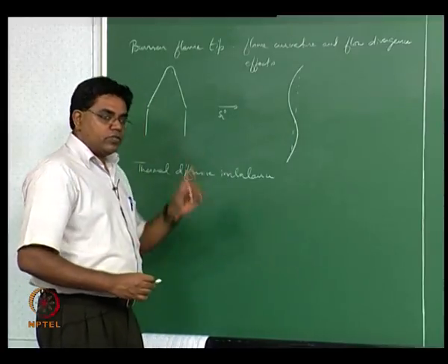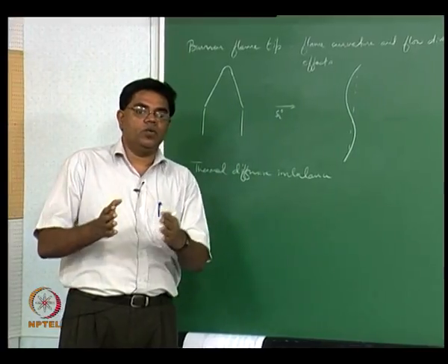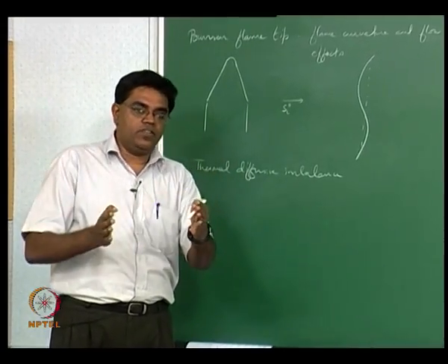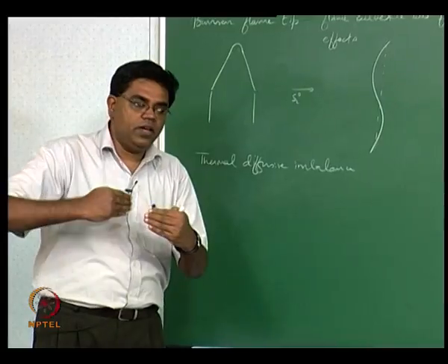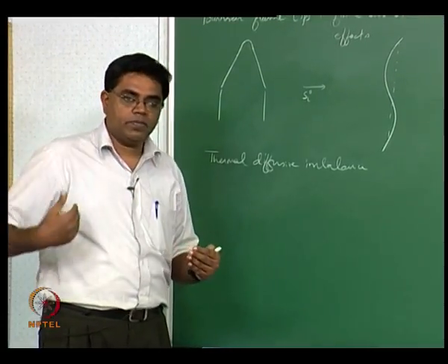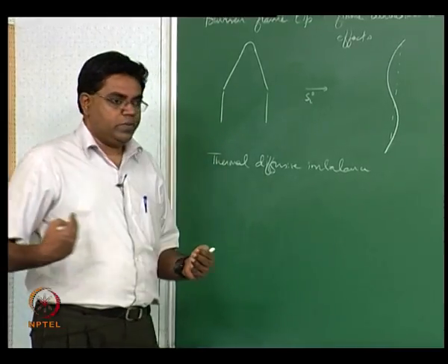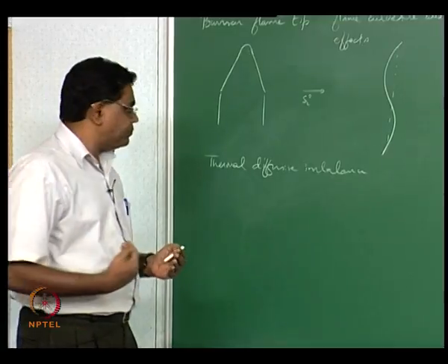Keep in mind what is meant by flame thickness. The flame thickness includes the preheat zone and the reaction zone, and the preheat zone is where the upstream heat conduction and downstream species diffusion happen, along with convection superposed on both the species mass as well as the enthalpy.